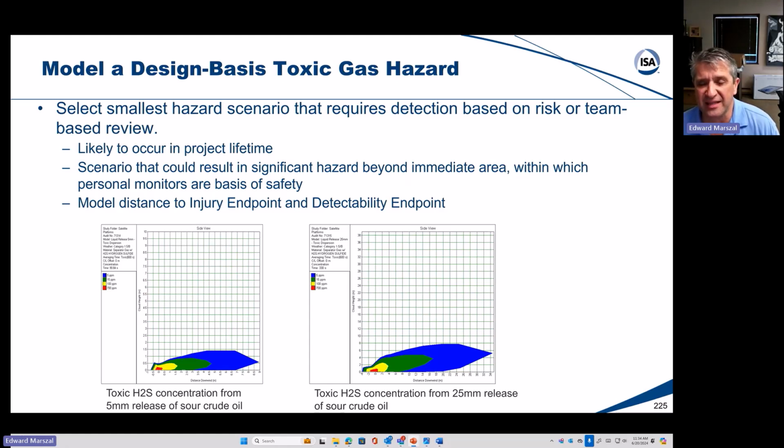But then again, it's also something where it's kind of easy for us to look at a layout qualitatively and know whether the movement of the detectors will actually significantly change the results. So on paper we would put 1 meter, but we would look at the layout, like on a plot plan, in comparison with the physical pieces of equipment to see if obstructions moved in front of detectors. But yeah, we would generally allow 1 meter for both fire and gas as our good practice.